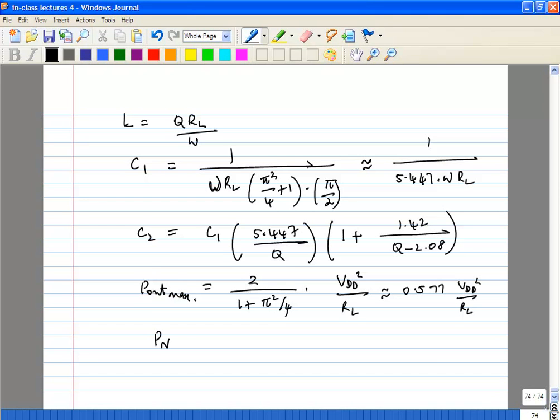So again, you can decide your output power handling capability. That happens to be 0.098, approximately 0.1. In the other case, even for class A and class B, we had 1/8, which is 0.125. So this is actually also a high stress amplifier.